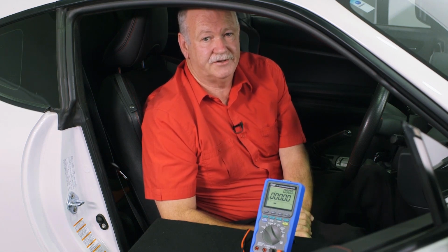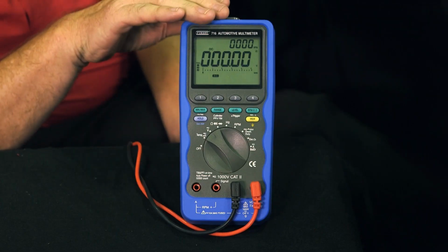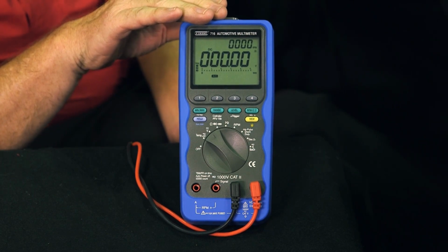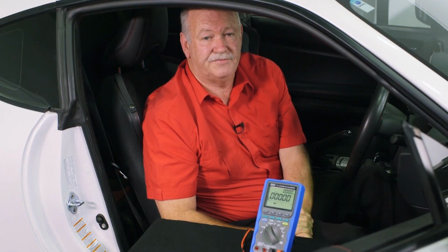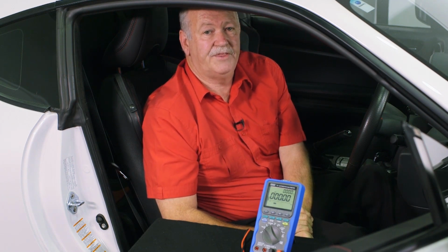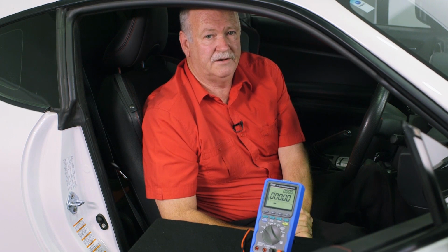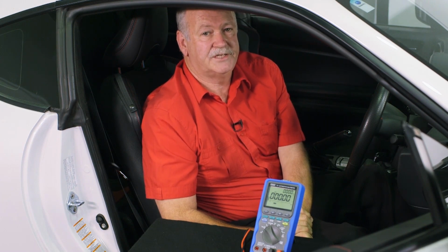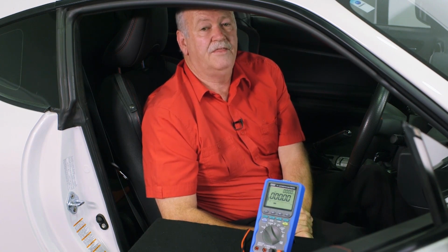I've got my leads connected to the signal circuit. We should see 12 volts because we're connected to a pull-down circuit and pin 16 on the DLC. But as you can see from the meter, I've got 0 volts. That would indicate that either I have a short to voltage or an open circuit. We'd test those exactly the same as we did for our ground circuit or our low reference circuit. And remember that if all your voltages are correct on each pin, the most likely cause is the accelerator pedal position sensor itself. If we have an incorrect voltage, that's our fault.